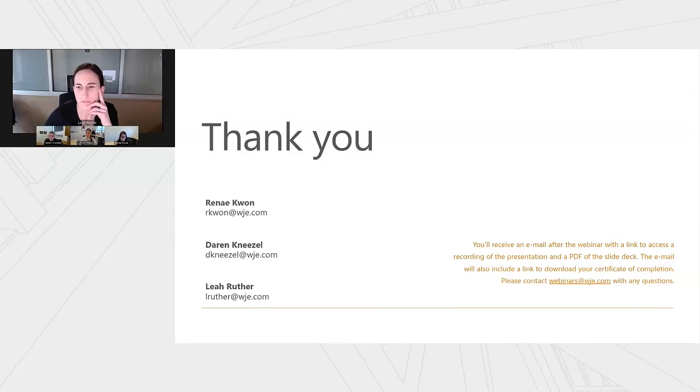I don't know if Daren and Leah, you guys have some other suggestions? Yeah, that pre-construction mock-up is important for various members of the crew to understand that you need certain requirements. You need to get good adhesive bond, and it's also important to understand the environment that you're going to be in. It's not a code requirement, of course, to do these mock-ups, but it's very helpful and to understand that everything's adhering as expected.